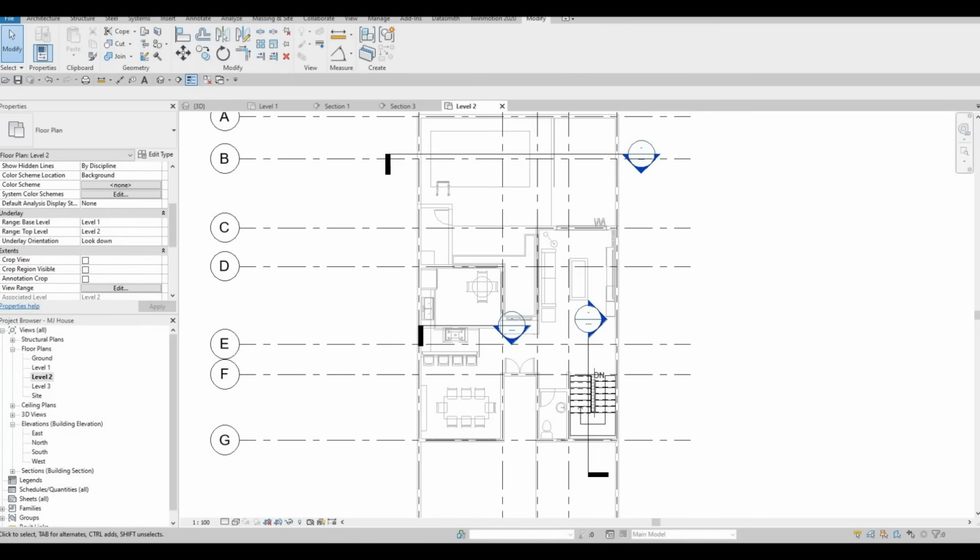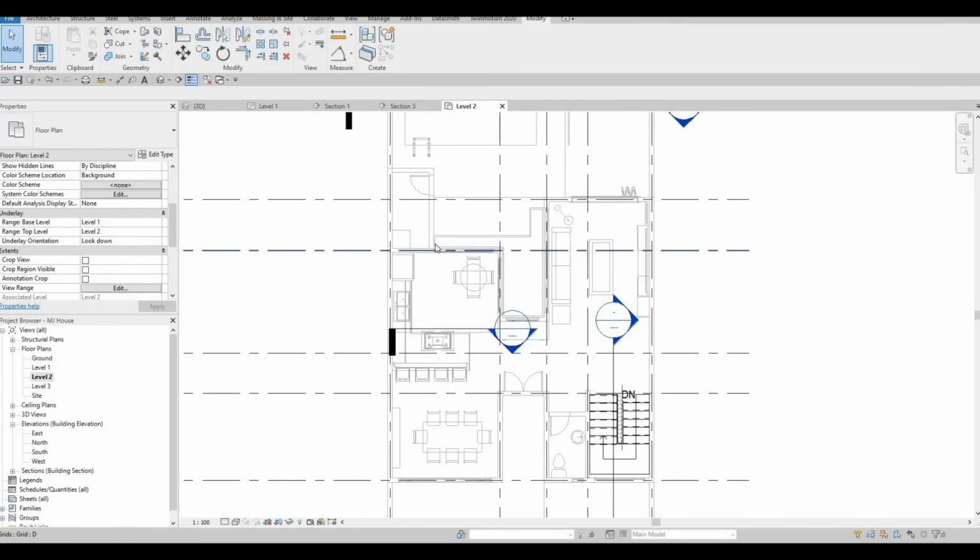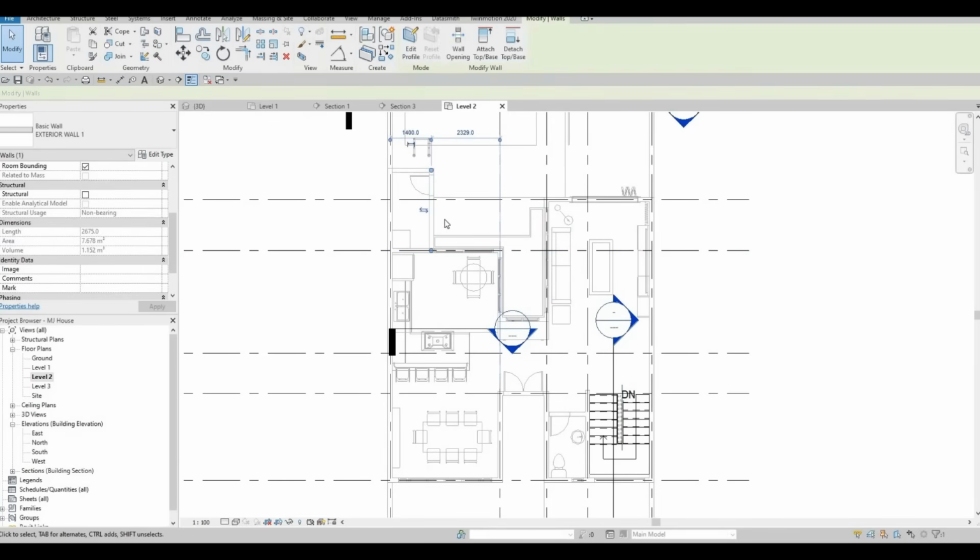So now we're gonna start off by adding an exterior wall. I'm gonna select this wall because I know this is exterior wall right here. But once I type in CS, that's to create similar, I'll be able to add it instantly right here.